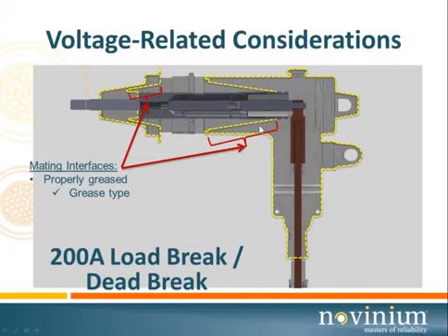Silicone grease does not migrate into the insulation. It's a misconception. People think of the interface drying out, that because the grease got absorbed in. It does not absorb in. Got to use the proper grease. The heavier grease stays in place. The amount of grease. We've got the right grease.